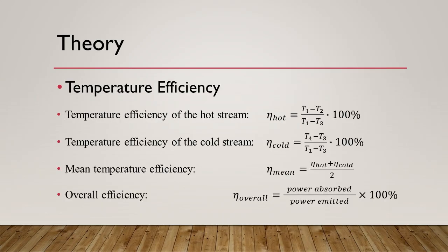A useful measure of the heat exchanger performance is the temperature efficiency. The temperature change in each stream is compared with the maximum temperature difference between the two streams. It is assumed to have a perfect heat exchanger of infinite size with no external losses or gains.